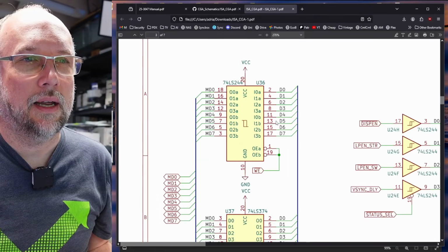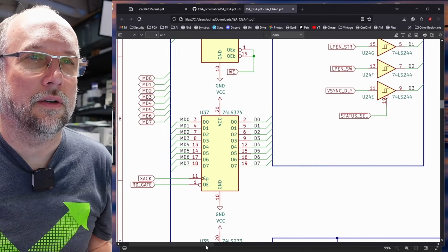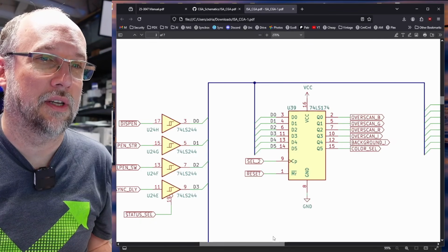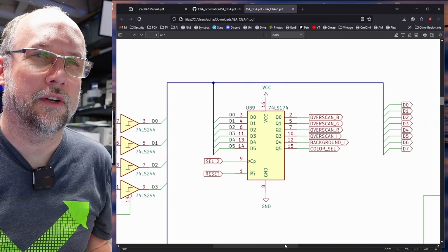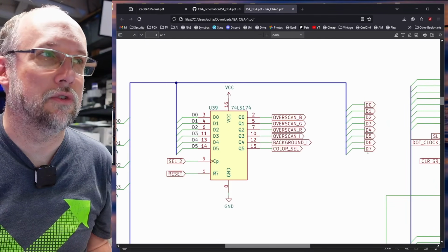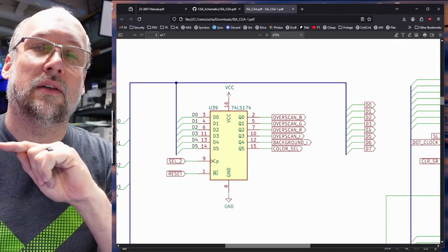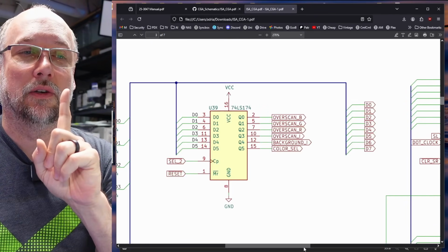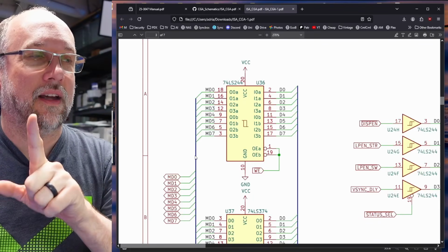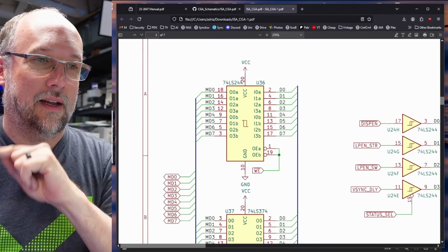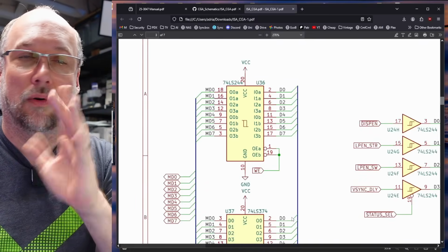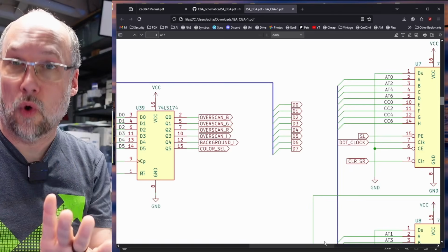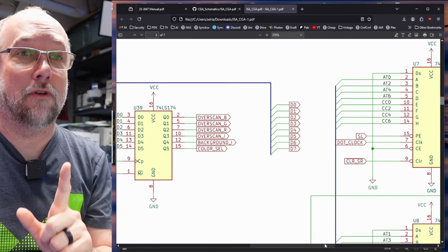And when we look at the output of these chips here, it goes into this chip here, which has to do with some overscan stuff, probably like border color, I'm assuming, but then it goes to D0 through D7. What D0 to D7 is on the CGA schematics is the ISA bus connector itself. So it looks like this is what's connecting the RAM to the ISA bus. So that's for the CPU to read or write from the RAM itself. So that's the path on the STB card we know is working, because the CPU has no trouble reading and writing from the card.